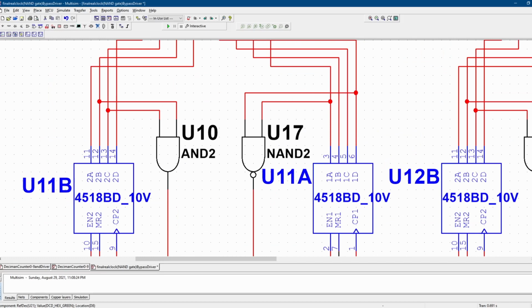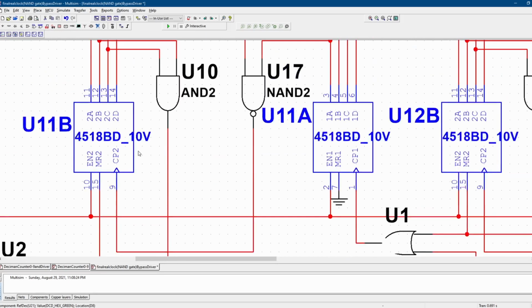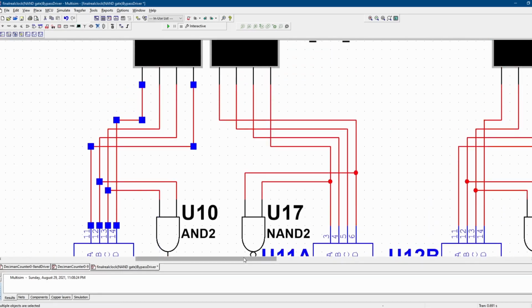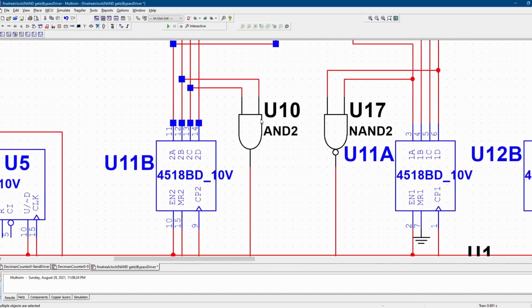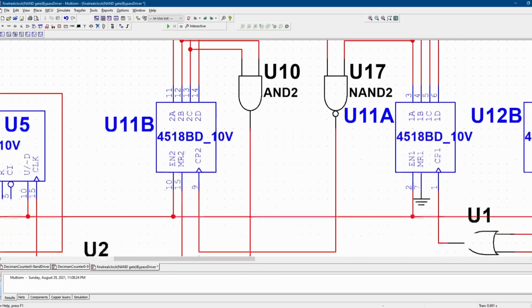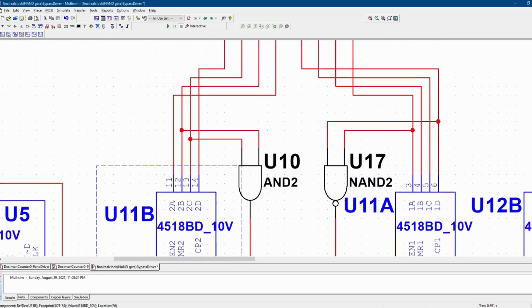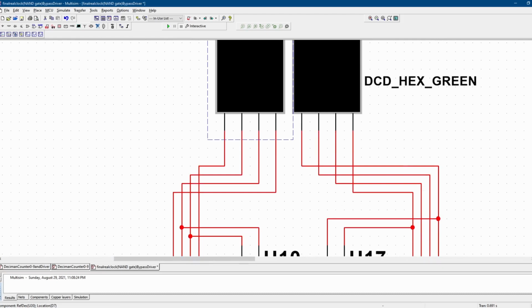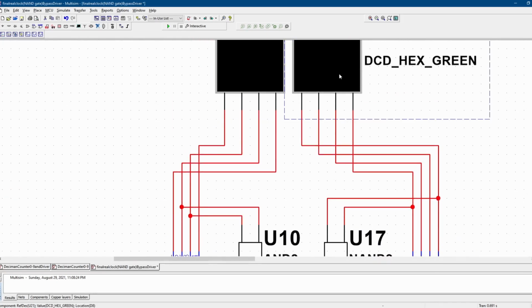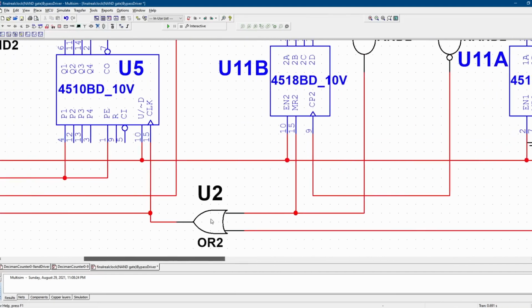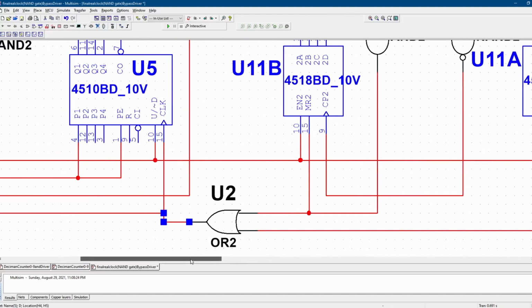So we take 9 on this side, place it into the clock of the following, and then we are looking at this output right here, and whenever it reaches 6, it triggers an output on this line here, and it'll trigger a reset. It'll immediately reset this one to 0, and alongside this one will go back to 0 as well, because it has to go from 9 to 0. And then if we keep following the line, it'll also trigger the hour.